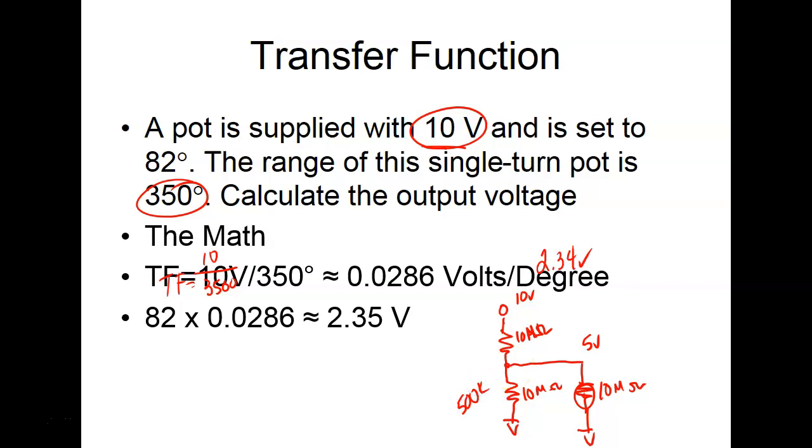You can never ignore this. We had a high resistance circuit, a high impedance circuit, out at US Steel. It came off electronic, called a mag amp. He went in there and wanted to measure the output of that mag amp with his meter. As soon as he put that across the mag amp, the whole line shut down, just like that. Because he didn't take into consideration that when he put that meter in parallel with the mag amp, the resistance dropped way down, and it thought it had too much current flow into the motors. It thought the motors were overloading, so it shut the whole line down.